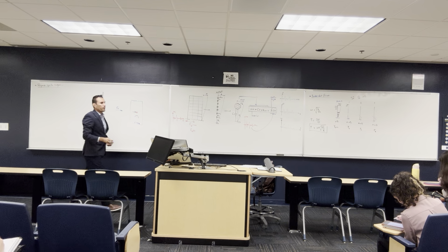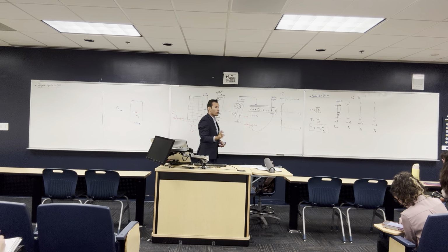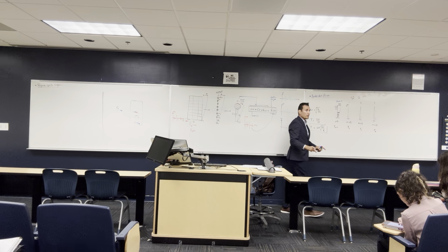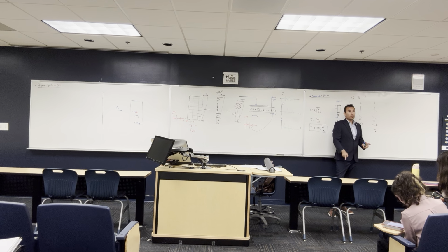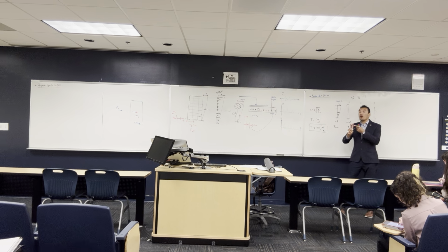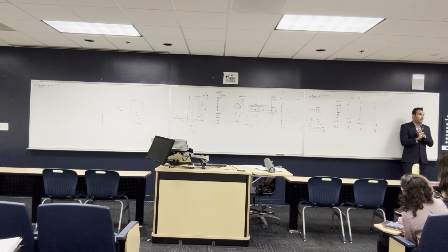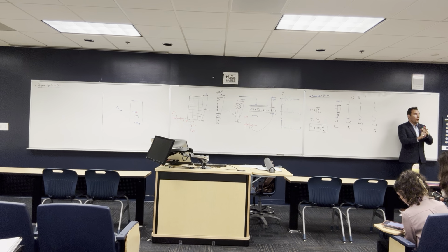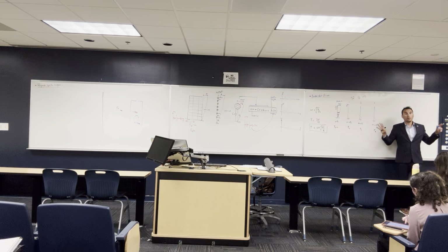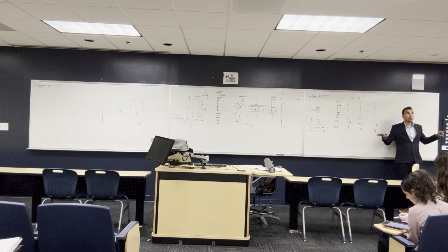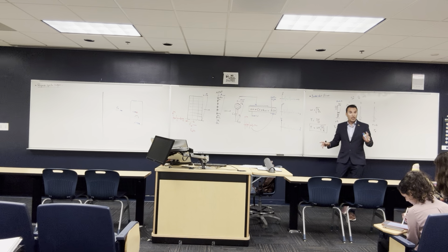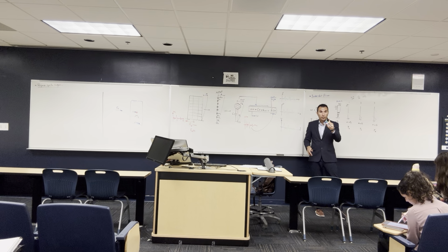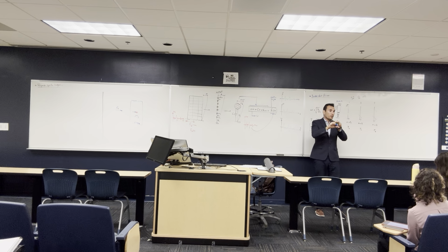Let's go back to the first 5 minutes from our last lecture. I told you, we as structural engineers, when we solve buildings, we are only interested in 2 things. We are interested in the internal forces in the building and internal stresses, but let's say internal forces, because if you have force, you can get stresses. And the deformations. That's what we do as structural engineers. We get forces in members, and we get deformations. That's your job. If you got that, you solved the structure. If you know how much force is in a structural member, based on the material that you have, you can find a cross section that can resist this force.